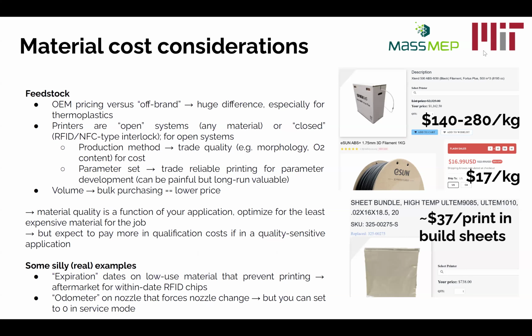In the case of powder, your powder morphology, the shape of the powder, might be less regular. The distribution of powder particles might be less narrow. In some cases, and the vendor will tell you this, the oxygen content might be different, which if you're making medical parts actually matters a lot. They buy a special type of titanium called extra low oxygen titanium to get better results at the end.